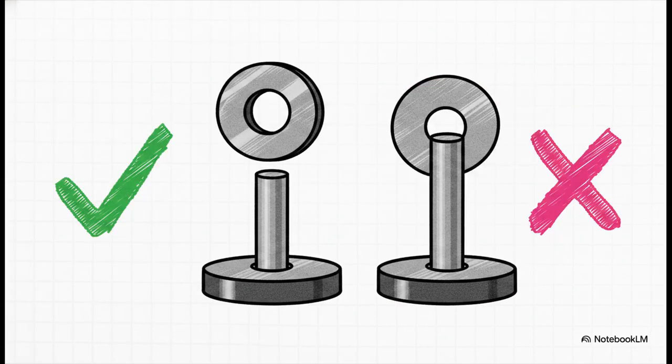This virtual condition calculates the exact dimensions needed for a functional GO gauge system. By sizing the pins of a GO gauge to this virtual condition, we use what's called an absolute gauge tolerancing, or basically a pessimistic policy. If the part fits over the gauge, it's definitively good. If it doesn't, it fails. This functional check is incredibly fast on the shop floor and ensures with absolute certainty that no defective parts ever slip through the cracks to cause assembly line stoppages.